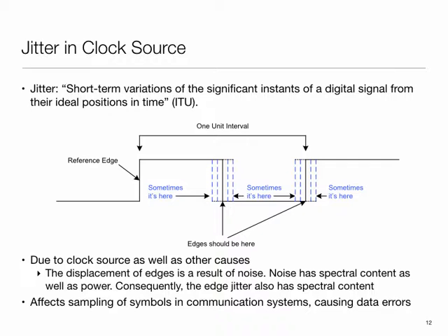So the upshot of all of this is that by the time we are done, depending upon the application, these issues begin to affect the application's performance. If your application is sampling the bits in an arriving packet, then the stability of the clock and the error in the clock edges affect bit error rate and how long the packet could be. Likewise, if you're using these things for, let's say, localizing something, GPS type multilateration, then it will translate into location error. So almost in every case, you can think of the error in time information translating into some sort of an error at the application level.